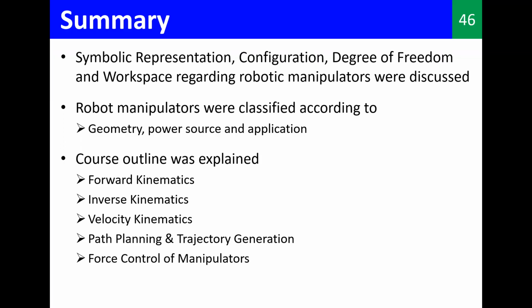So we'll talk about forward kinematics. So we give some theta 1 and theta 2 and find out where our end effector is going to end up, right? But the most important question is the inverse kinematics. We want to send the end effector to some position and an angle, and what are the inputs that we should give to the joints or the motors, right? What is the theta 1 and theta 2? And then the same concept but in velocities, right?